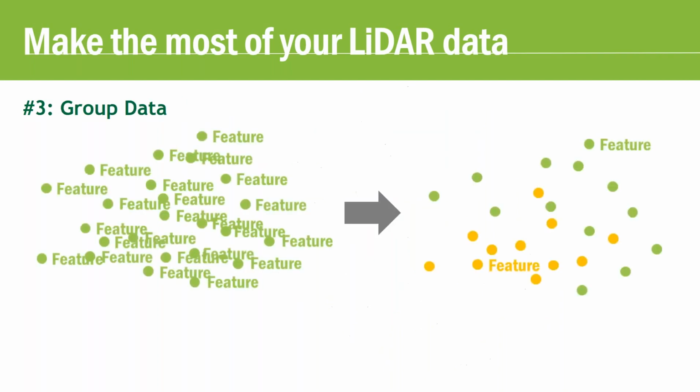The final point and idea with LiDAR data is around grouped data. Now, this point really only applies to ASCII data sets. When importing these, it's important to leverage the combined features options that are available during import. And this, again, is all about not taking up as much memory. Today, Jack's going to be using an LAS file. And with this, it automatically imports as grouped features.